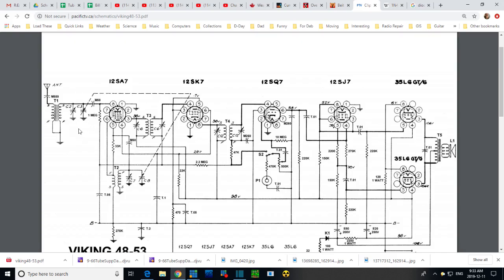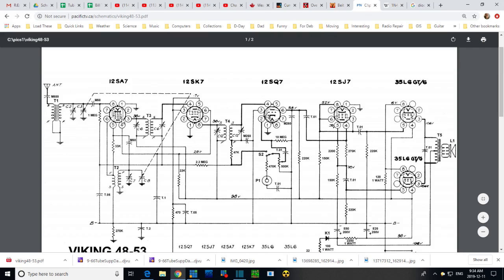So the better this is, the better off the radio. Absolutely. So you notice the first tube encountered is the mixer tube. So this qualifies as a fairly simple radio, probably prone to some image problems. That's probably the case. And that's why I'm happy to experiment with this radio, because I realize that already, that it's susceptible.